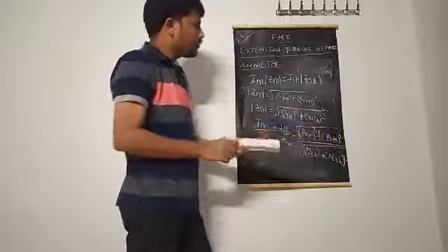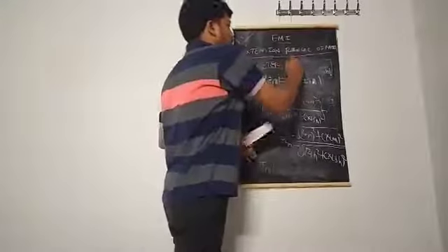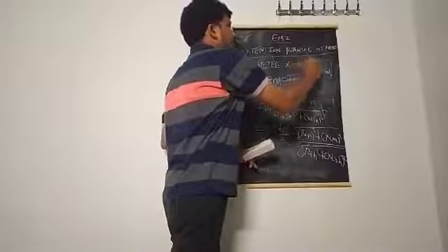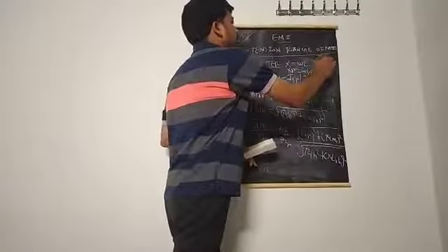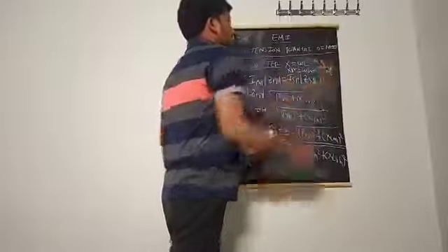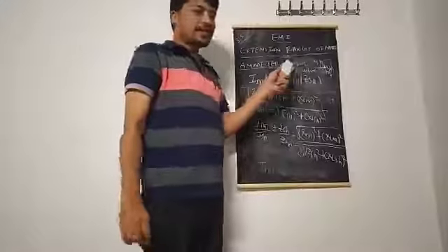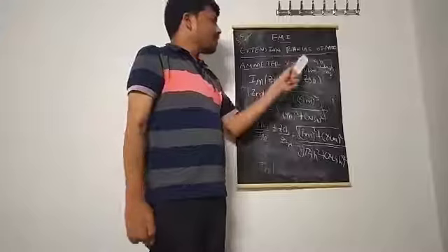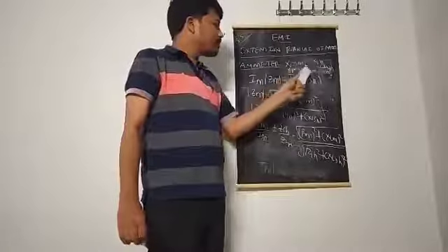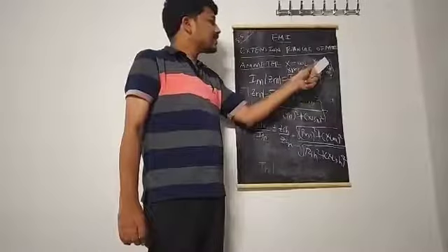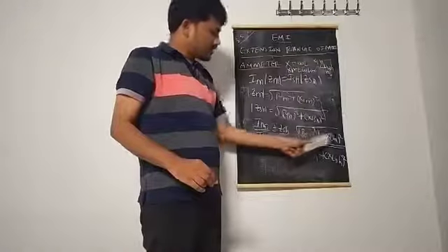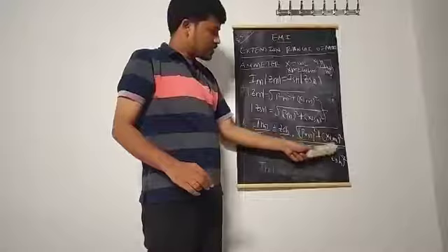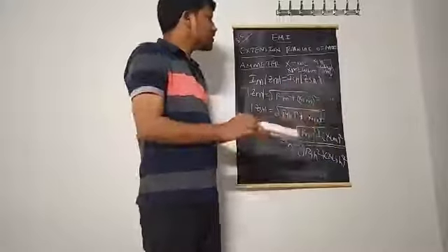We know that what is X? Reactance. Reactance can be written as omega L. Similarly, Xm is omega Lm. Similarly, XSH is omega LSH. Is it clear? So, X is nothing but reactance, that is omega into L, 2 pi f L. Xm is omega Lm, XSH is omega LSH. Substitute Xm and XLSH values in this equation.